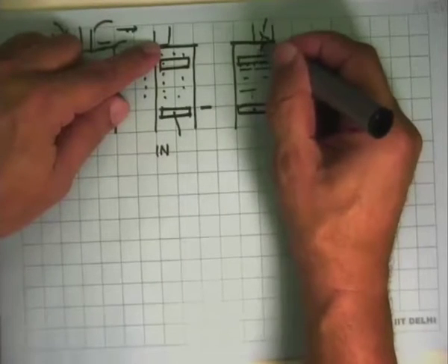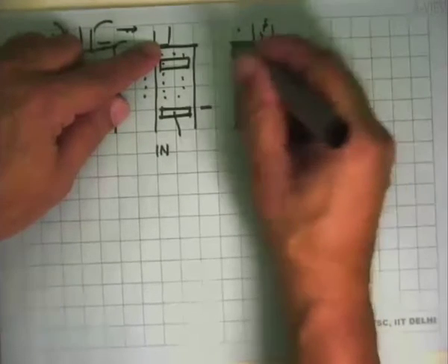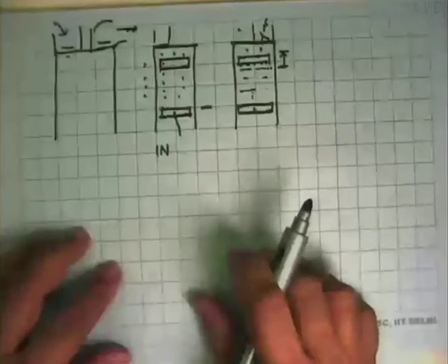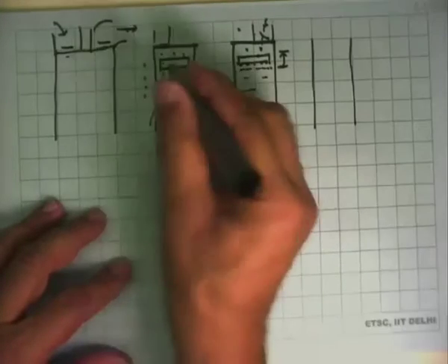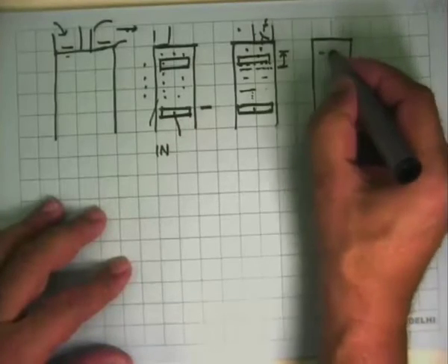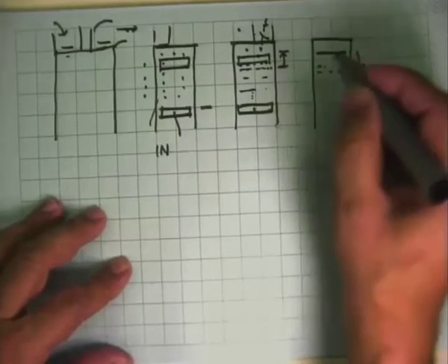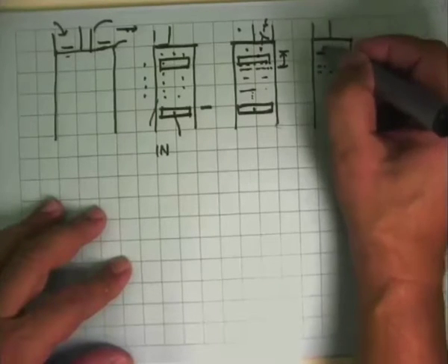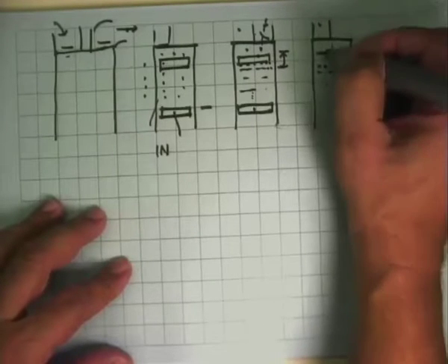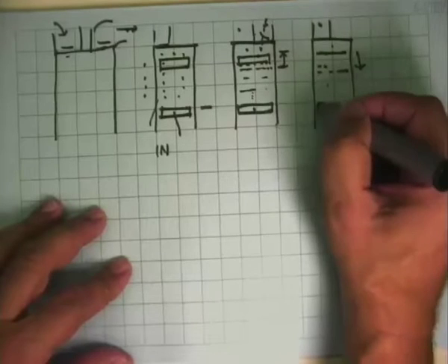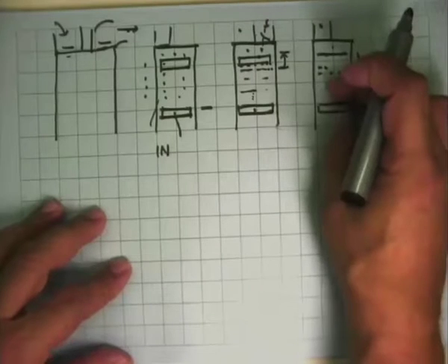After it reaches the top, this pressure is equal to this pressure, this valve closes, this pressure is greater than the inlet pressure, this valve closes. Now you have a closed system over here. And then what happens? The piston now begins to move back. But in moving from this position, as it comes down to some position over there, it is a closed system in which the pressure inside is decreasing. And it will decrease up to a point when it is equal to this pressure. After that, when the pressure here is less than this pressure, then from there till the bottom part, it will suck in the fresh refrigerant.